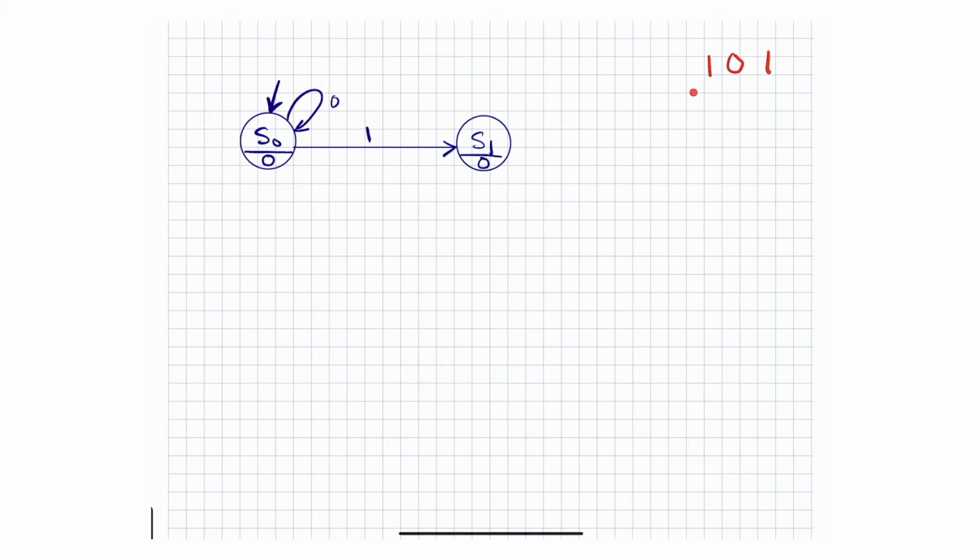But I usually go through this whole sequence and then fill out the rest of the arrows or transitions. So what I'm looking for is a 0. Hopefully you go in here, okay, and then we do that here. All right, and I have an S2, and that's basically 0. So I'm going to write it on the side in here. I believe S0 just remembers 0, S1 remembers the very first 1, and S2 remembers 1 followed by 0. The output has to be 0 at this particular point.